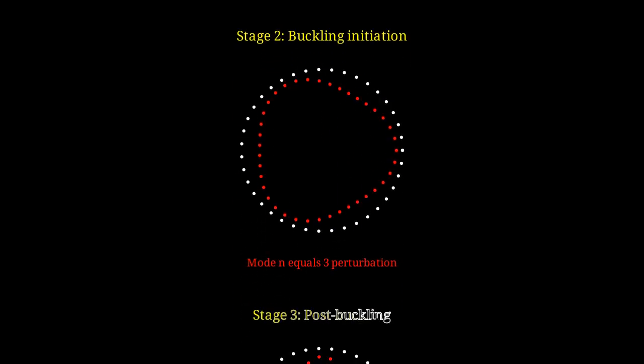Stage 3 is post-buckling. The deformation grows into a large amplitude mode. Here, mode n equals 4. The shell exhibits significant folding and bending. Energy is now stored in bending deformation, not just stretching.